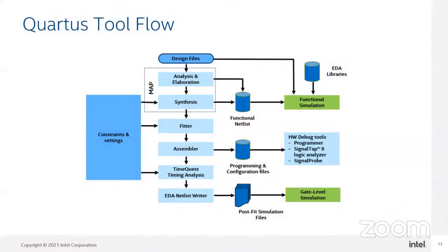I'll just show you one small logic, so you will get an idea. What we were doing for the past 2 days is we need to develop the code. We perform analysis and elaboration. We do synthesis, filter, assembler, then we do timing analysis. Then we need to perform hardware debugging. Till now I showed you the programmer, Signal Tap logic analyzer, signal probe, everything we have seen.